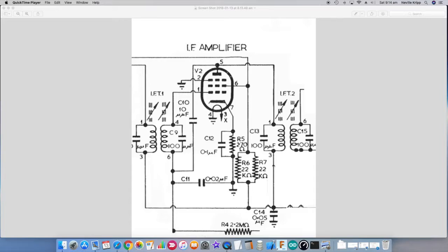The voltage coming through the resistor is actually from the AGC circuit and is used to automatically control the gain. So if you get a large signal, it will tend to reduce the gain of the IF amplifier so that it doesn't overdrive the whole receiver. The IF signal will be appearing on the valve grid terminal on pin 1.